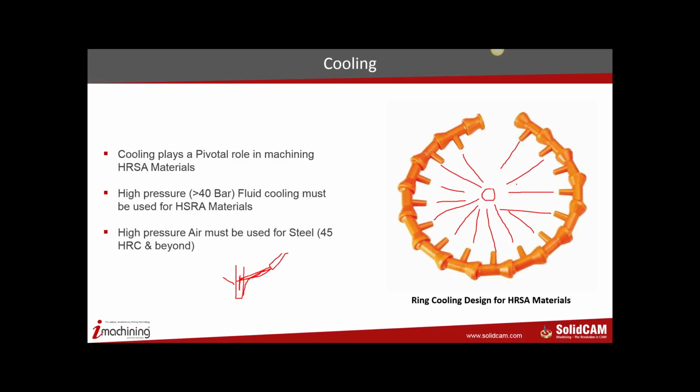Steel is not a poor thermal conductor. It actually is a pretty good conductor. So the heat that is generated is always in the chip. So here, we are not supposed to cool the tool, but we are supposed to evacuate the chip. In such cases, using fluid coolant can actually become catastrophic for the tool because the tool is slightly hot. If you try to cool it immediately, it could develop cracks, micro cracks. So the goal in steel is to evacuate only the chips.